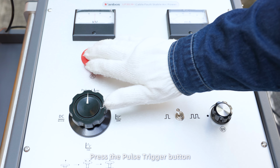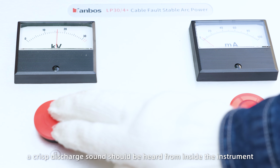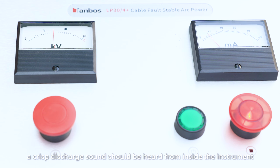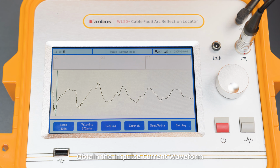Press the pulse trigger button. Observe the voltmeter for a significant kickback. Simultaneously, a crisp discharge sound should be heard from inside the instrument, indicating the fault point is fully broken down. Obtain the impulse current waveform.